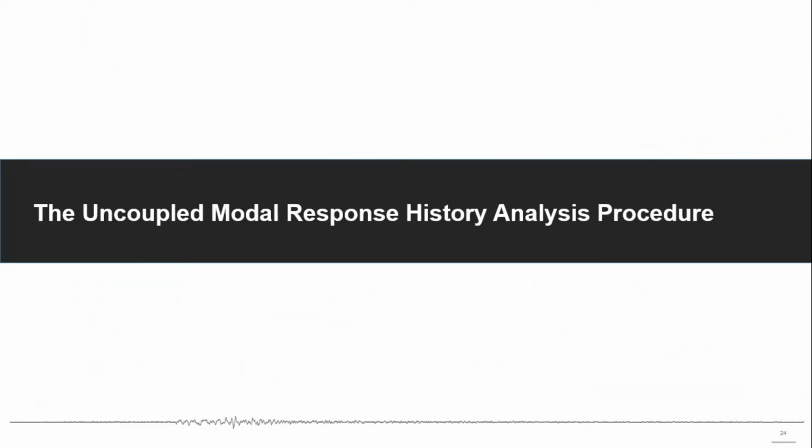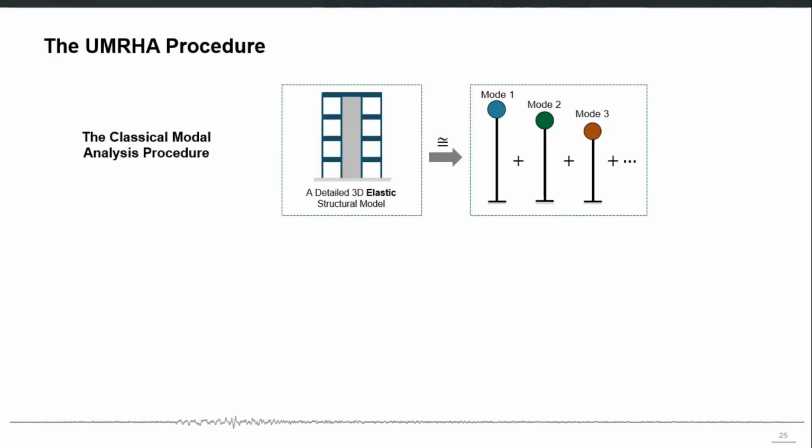So let's first discuss the uncoupled modal response history analysis procedure, and then we will use that procedure to understand the modal pushover analysis. So the UMRHA procedure can be seen as the natural extension of the classical modal analysis procedure to nonlinear systems.